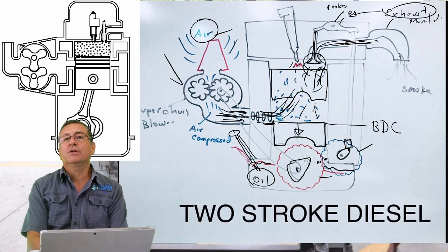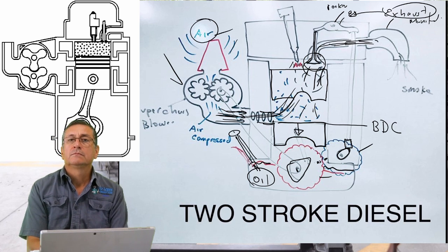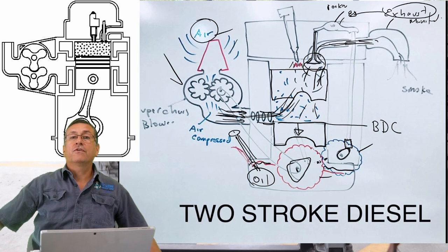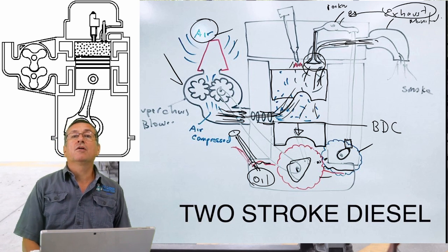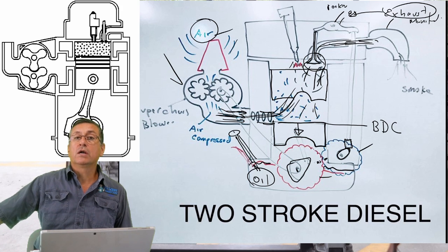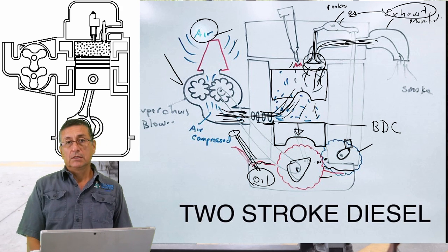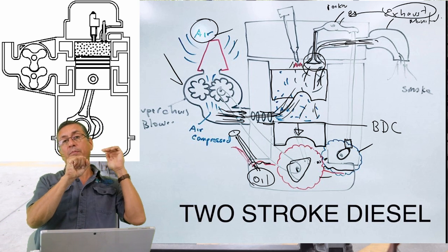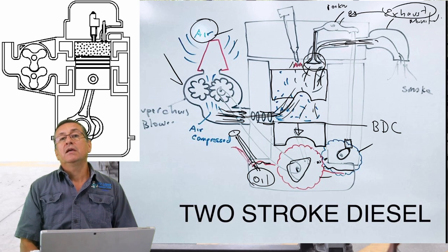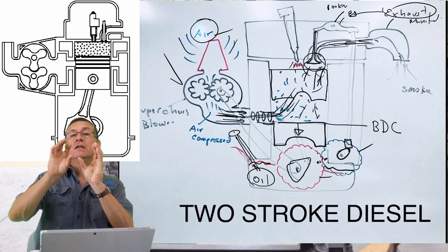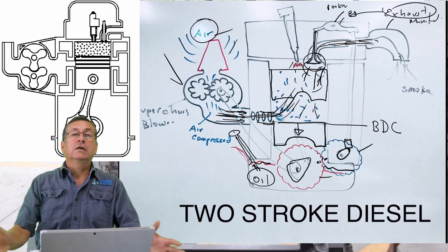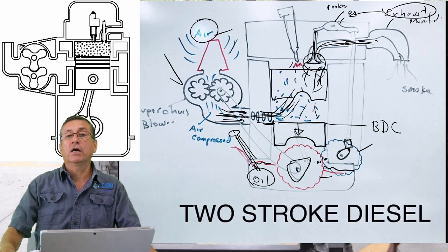The two-stroke diesel engine only has exhaust valves, only has injectors on the head, and the input of fresh air is at the bottom, on one side of the block, where the blower or supercharger is located. The air enters at the bottom. When the piston reaches the bottom dead center, those holes are open and the air enters over there. Immediately the fresh air enters the cylinder, pushes the smoke out, and the gases go out, and the cycle continues and continues and continues.